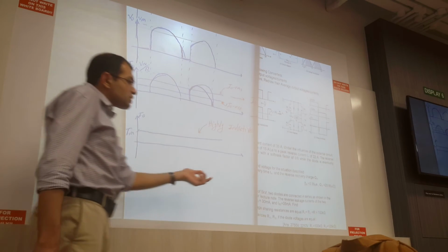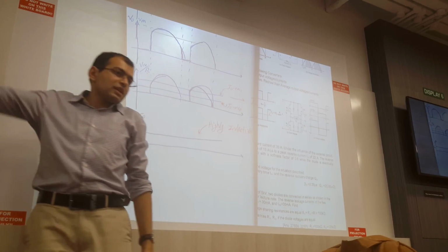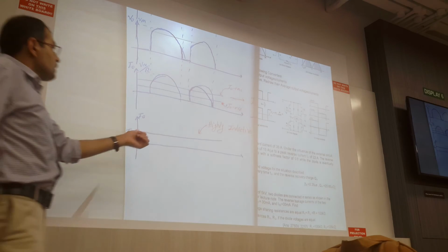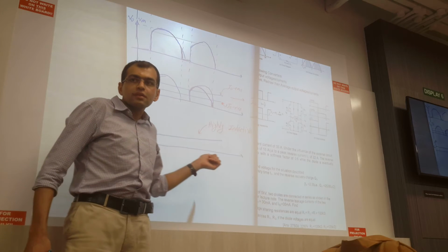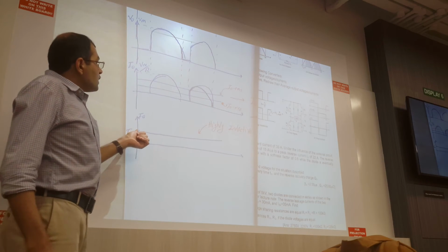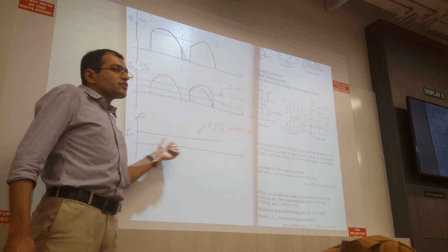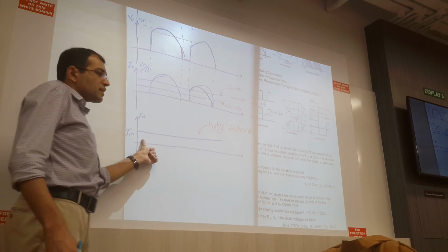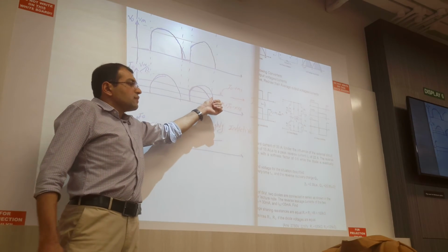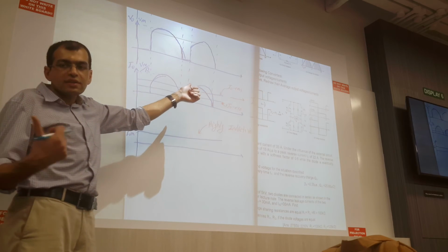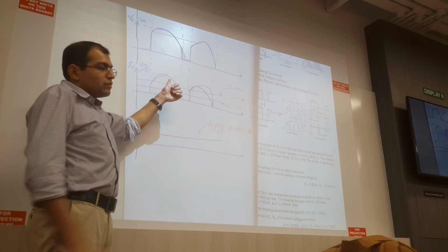And for the same question, if I have a highly inductive load, with the same reasoning which I just told, the current will become a constant. The question is asking you again to calculate the RMS and average of this current, which, with the same method as the first section, you can calculate.